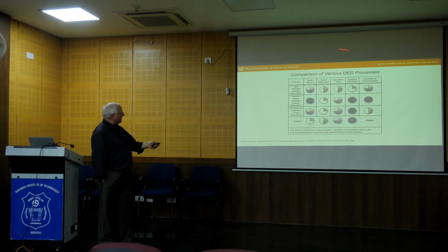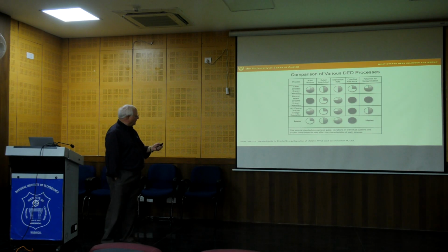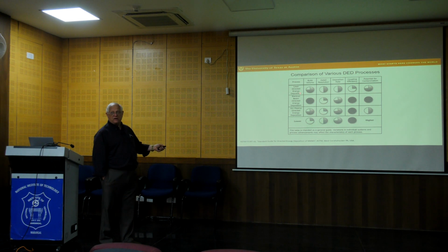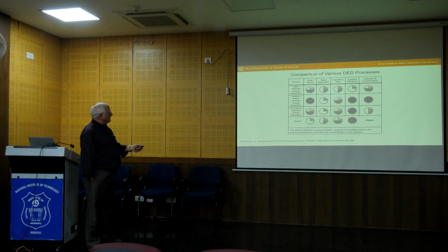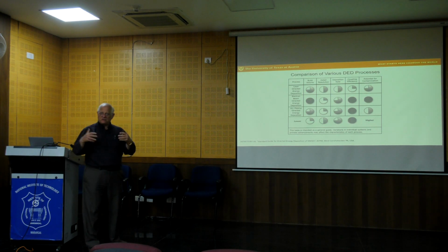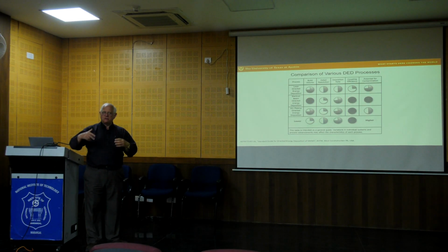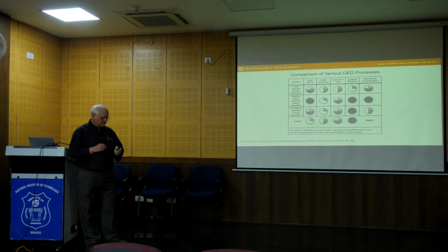Okay, so having said all that, I think this is a very useful table for distinguishing between the laser energy source for directed energy versus the electron beam versus the plasma arc type processes. What it shows is these types of factors: the build volume, basically how big the part is, the resolution of the part surface, how fast we can deposit, and the coupling and efficiency, that is, how well does the energy beam couple to the feedstock, which is important from an energy perspective.